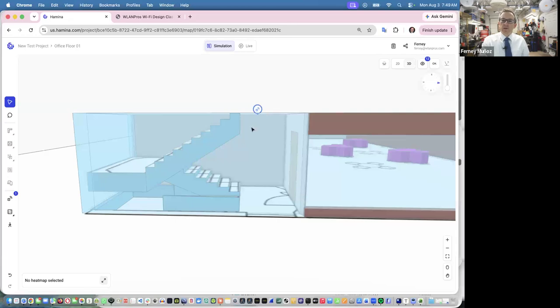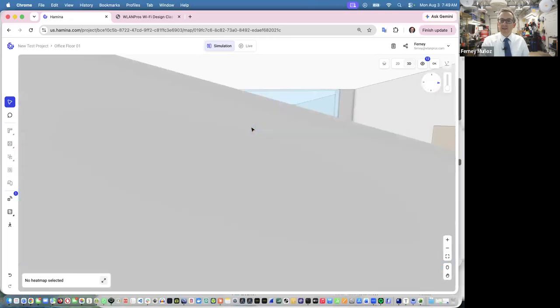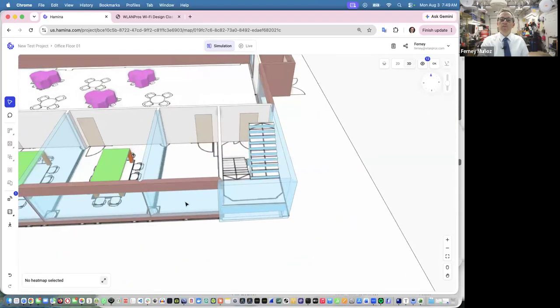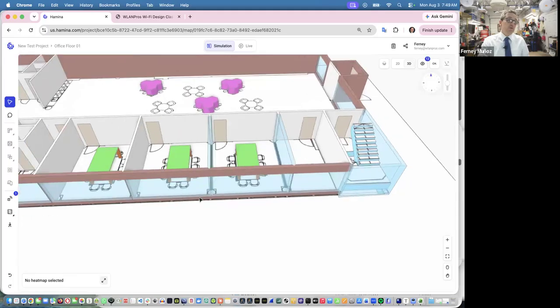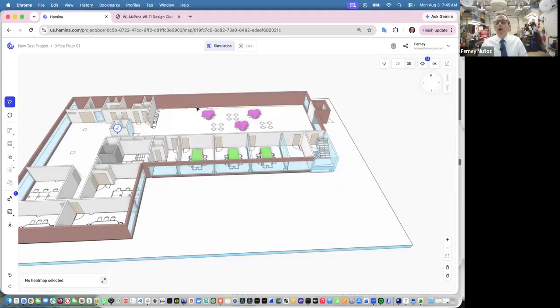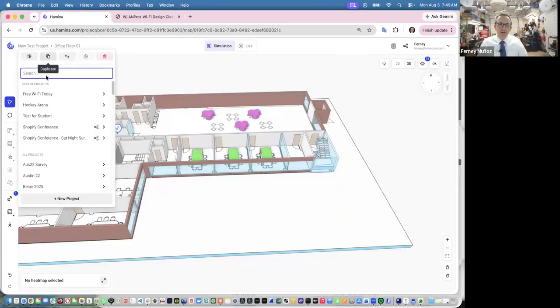And then we also learned how to create these inclined spaces, stairs, slopes, raised floors, and then we added stairs to it. Tomorrow, or the next session, we're going to learn how to create a building, how to add more floors on top of this floor or below this floor, how to align those floors, and how to create a hole in the floor to have the effect of an atrium, how to design air ducts and signs, and show you how to create things.